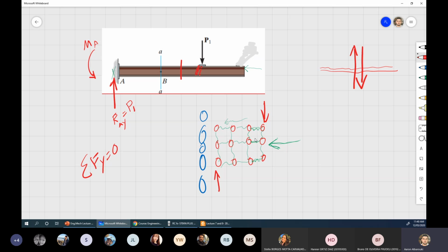The point where we talk about the ultimate failure or ultimate rupture depends on what direction we are applying this force. Imagine I'm applying a very high tensile force here, tension force. I'm trying to pull the ice a lot. First of all, these springs will stretch, and that's the yielding point. And then if I continue past that point all the way, I reach a point where these springs will rupture. And that's what we call the ultimate failure point.